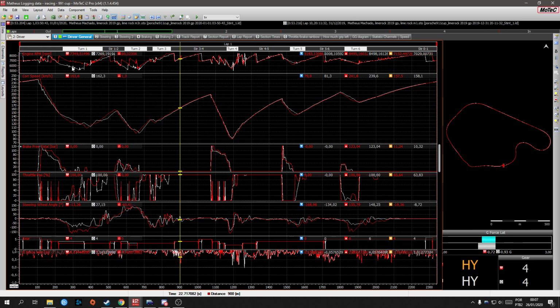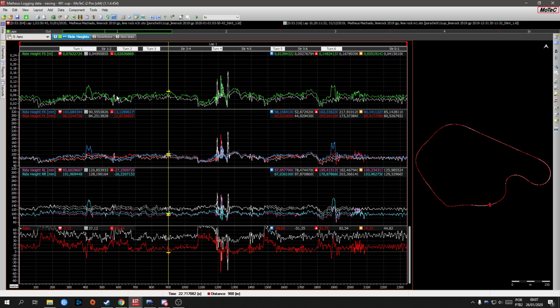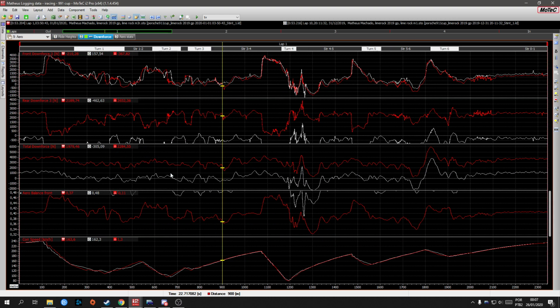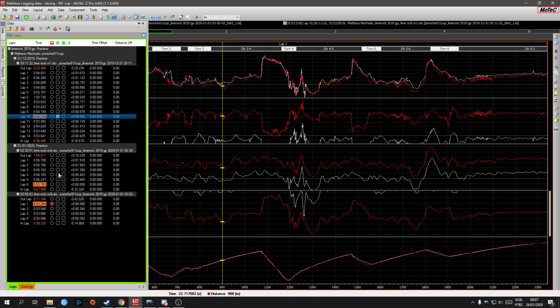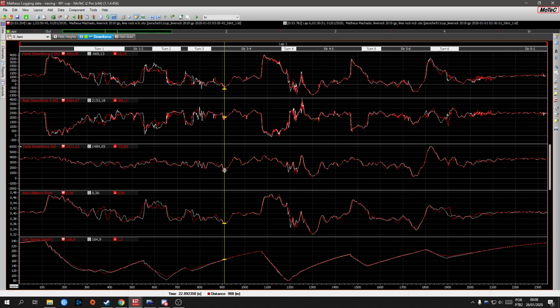So that's an indication of severe oversteer with the car. And look, those are the same wings being used. I didn't change the wing between all these data sets. So here it was a middle ground. It was 115 millimeters at the rear, and the red is at 100. So you can see that it started to